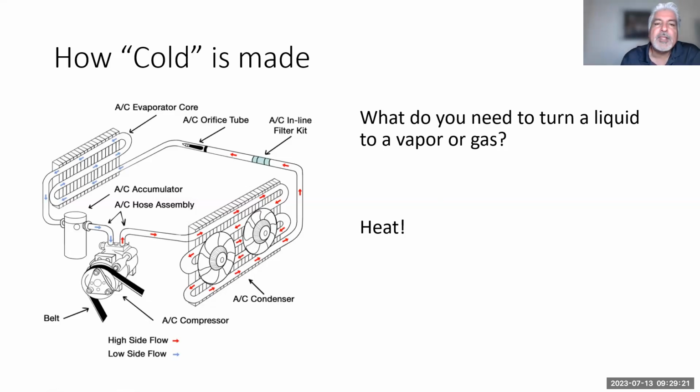It's very frustrating when a customer pays for a full AC rebuild, meaning the compressor was replaced, the orifice tube or thermostatic expansion valve, maybe a condenser and the accumulator receiver dryer, and it won't go more than 6 months. You see catastrophic failure of the compressor again, because there was still contamination that took out the compressor.